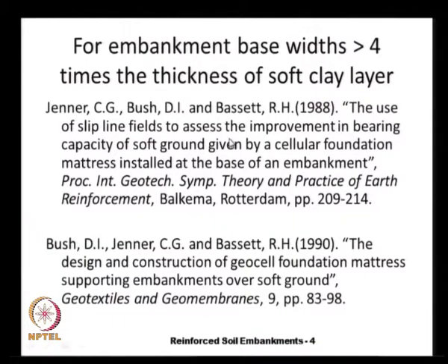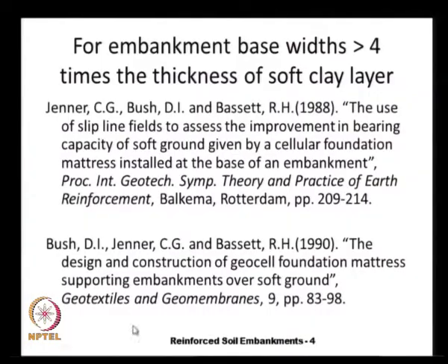Actually, the first paper is more on theoretical aspects on how to adapt the slip line field method for calculating the bearing capacity improvement below the Geocell reinforced embankment, and the second paper is more on how to apply that theory for the design, and then they have also shown the application of this method for construction of a large size embankment, and they also provided a lot of field data in this paper, and they claim that this method of design is quite successful in many situations where they have achieved uniform settlements, and the bearing capacity was found to be much higher than what it would be otherwise without our Geocell mattress.